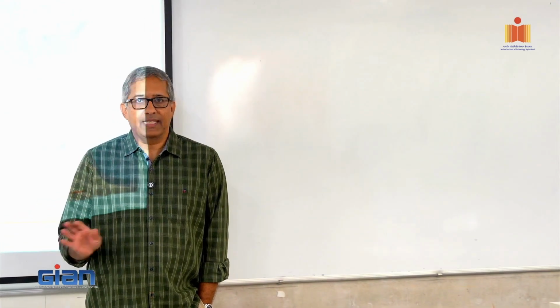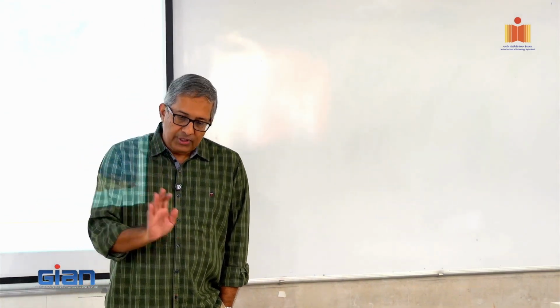Yeah, we had a whole Gyan course that delved in a lot of depth in that matter. At this point of time, I'm not able to give that fine detail. There are enough papers on that. And at this point of time, we've come to a stage where we can develop these mixes in a scientific manner. We cannot follow the same mix procedures as laid in 10262, which is our base guide for concrete mix design. That will not work. But procedures are evolving, looking at the aggregate, the cement content, etc. Now we can develop 3D printable mixes.